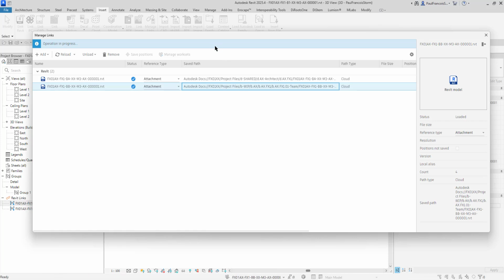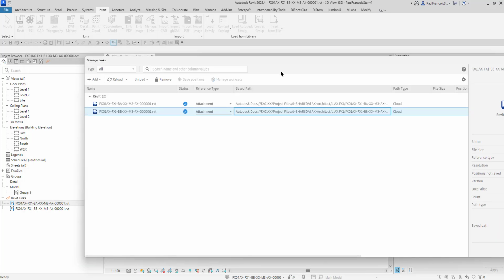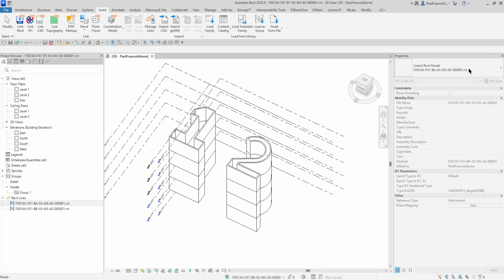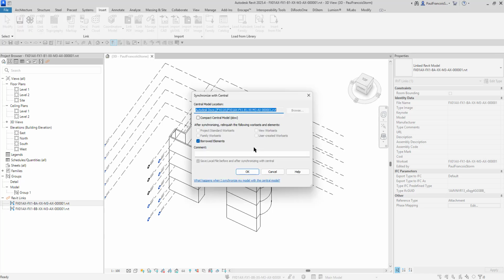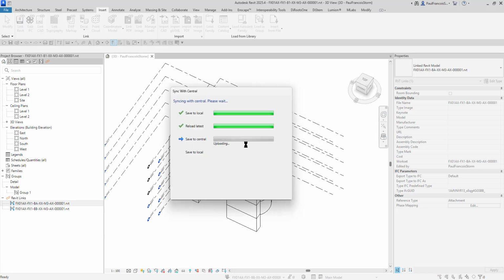So what you should see next is that the typical rooms now appear without the doors because it's repathing to an old file. That's fine. We'll then also synchronize and modify these settings and relinquish all our work sets.